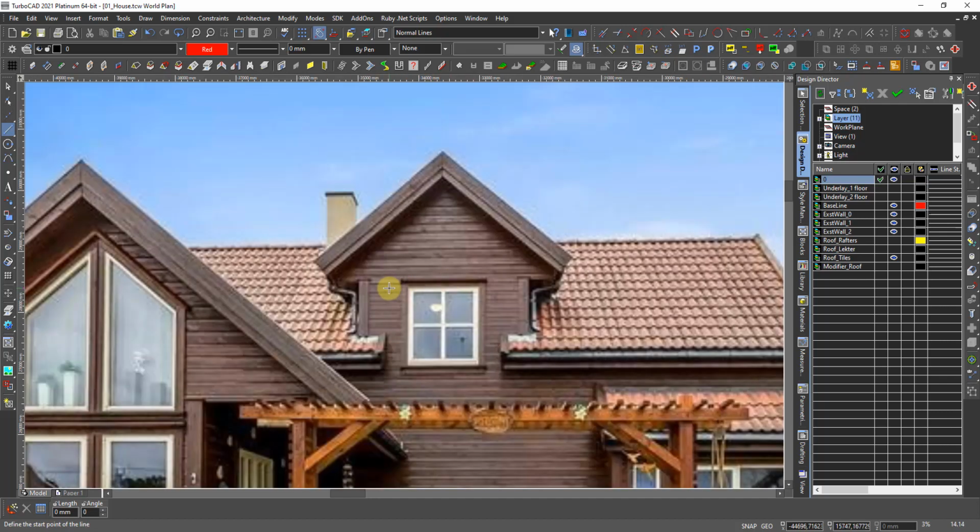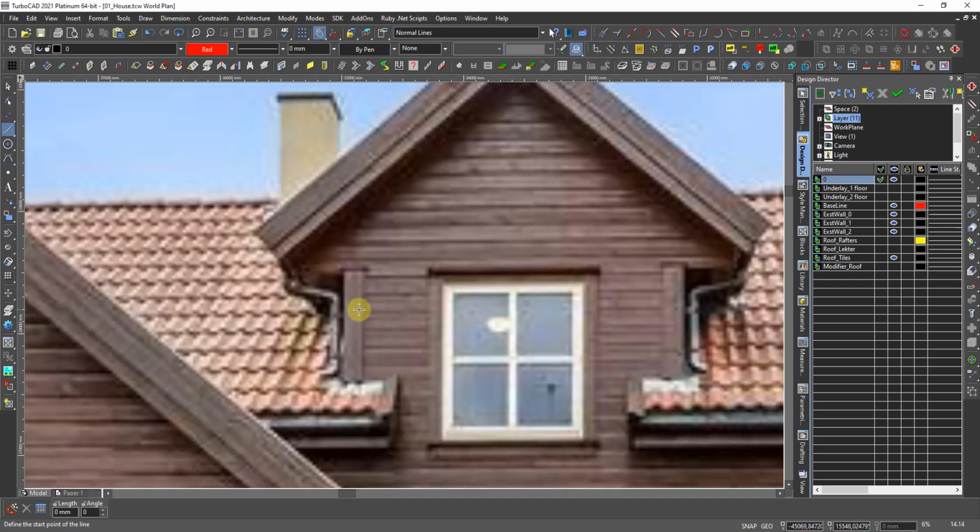Then I take this and I just dimension it. This wall is also, with this kind of cladding, normally there will be 54 millimeter from outside cladding to where we meet the framework. So then I take about 5 centimeter in here, and I dimension to about the same place on this side, something like that.